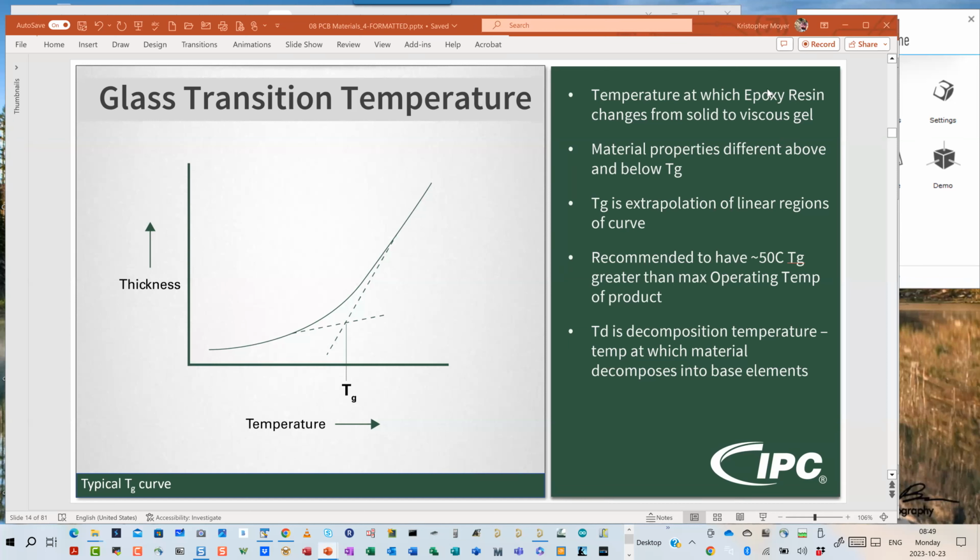Right? Okay, thanks. Infinitely varying possibility of what could happen. The accelerated testing could cause your FPGA to have an improper output state change, or maybe not go high enough on output state change, and so you get an unknown race condition. All kinds of problems could happen where you exceed the expected max operating temperature of the parts.